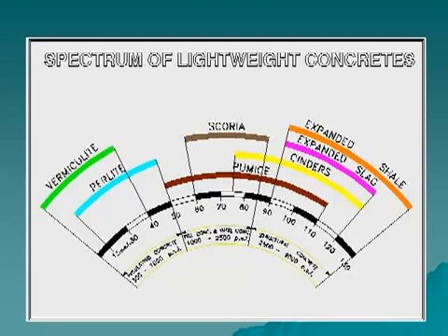For example, a search of Dodge construction data using the term lightweight concrete usually returns a majority of specifications referring to insulating concrete. Expanded shale lightweight aggregate is generally not used to make low-strength insulating or fill lightweight concrete. It is recognized that expanded shale aggregate is an excellent choice when it comes to manufacturing structural lightweight concrete products.